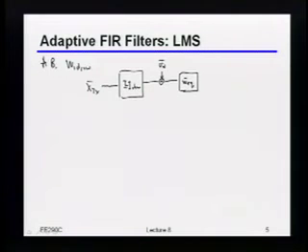In this case I'm just going to assume the equalizer is on the receiver, but we'll come back and talk about how you do the transmitter in a second. After I've done all that, I'm going to do this whole operation to figure out the analog received voltage sitting after this equalizer, at one particular sample point. Obviously, as you change the sample points, you'd fill in different values into this transmitted X over here, and that would give you different values for the final analog received voltage.